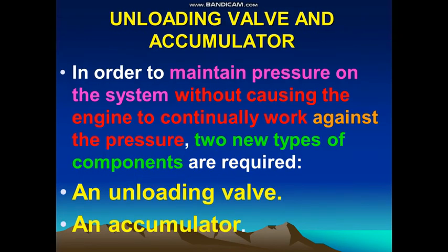Unloading valve and an accumulator. In order to maintain pressure on the system without causing the engine to continually work against the pressure, two new types of components are required: the unloading valve and an accumulator.